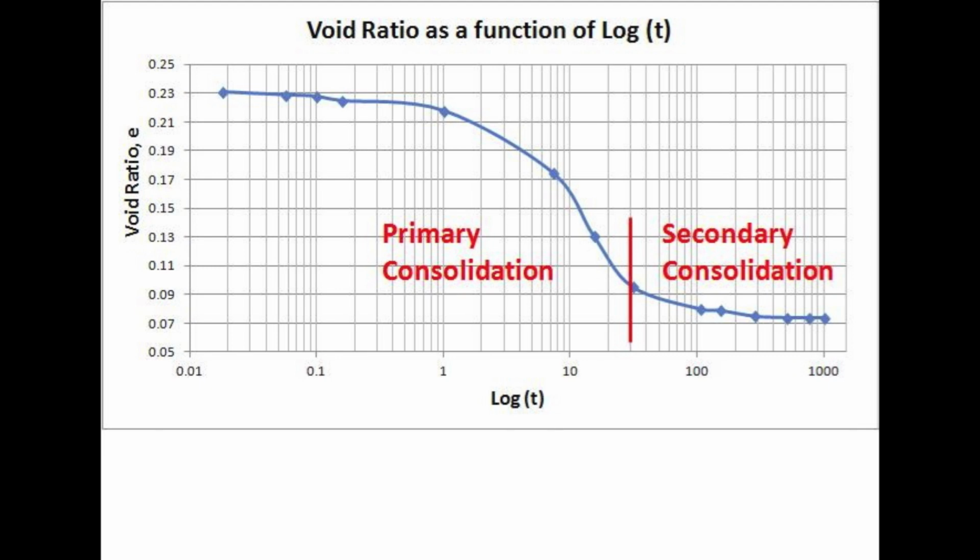Fine-grained soils are the most prone to settlement or consolidation issues because of the number of voids available for expulsion. Fine-grained particles have larger surface areas than coarse-grained particles, thus more voids. Primary consolidation is a serious and dangerous issue that must be addressed when building over silt or clay layers.